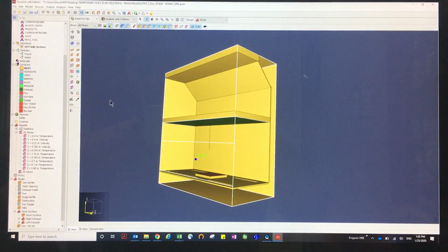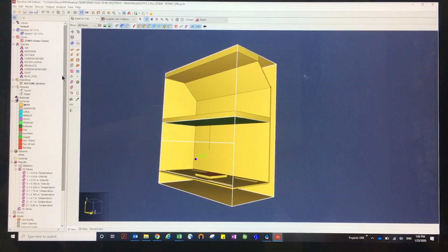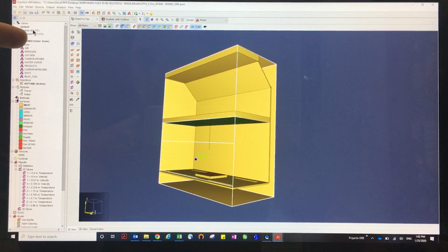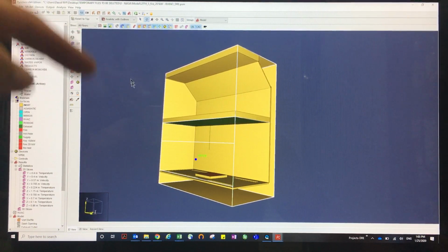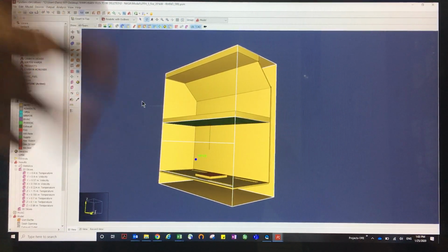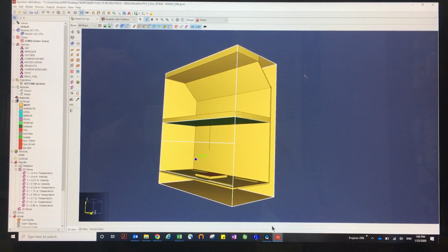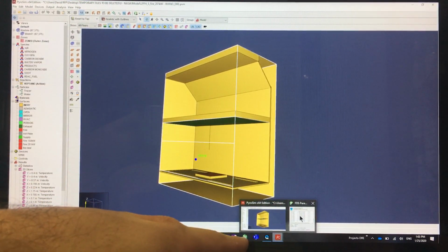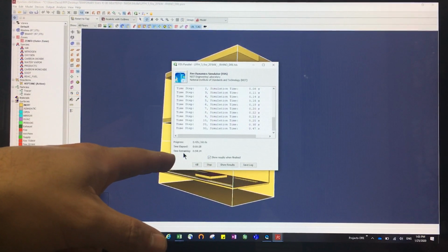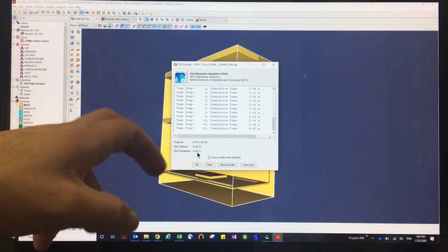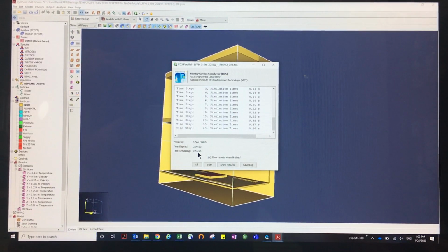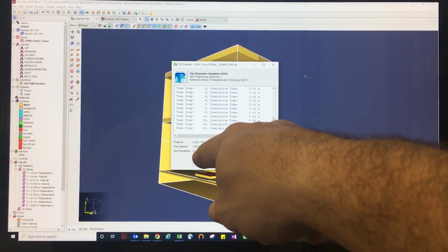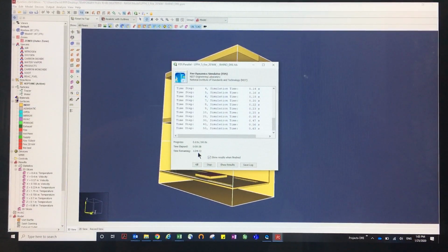So this mesh, while it runs, you can actually keep making modifications. And if you hold on, so this mesh is huge, 67,000 cells, and I wanted it to do it for 60 seconds. So that thing is gonna take forever. Here, double click here. It's telling me that time remaining is estimated at 54 minutes, and it changes. You see, it increases as it calculates more and it realizes that it needs more data.